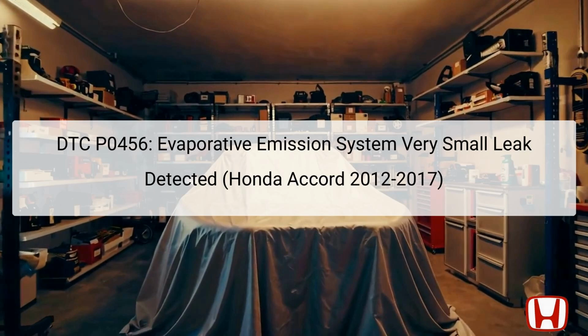The diagnostic trouble code P0456 indicates that the Evaporative Emission (EVAP) system has detected a very small leak. This code is crucial for ensuring that harmful fuel vapors do not escape into the atmosphere. The components involved in this system include the EVAP canister, which captures fuel vapors from the fuel tank, and the fuel tank pressure (FTP) sensor, which monitors pressure changes in the fuel tank.